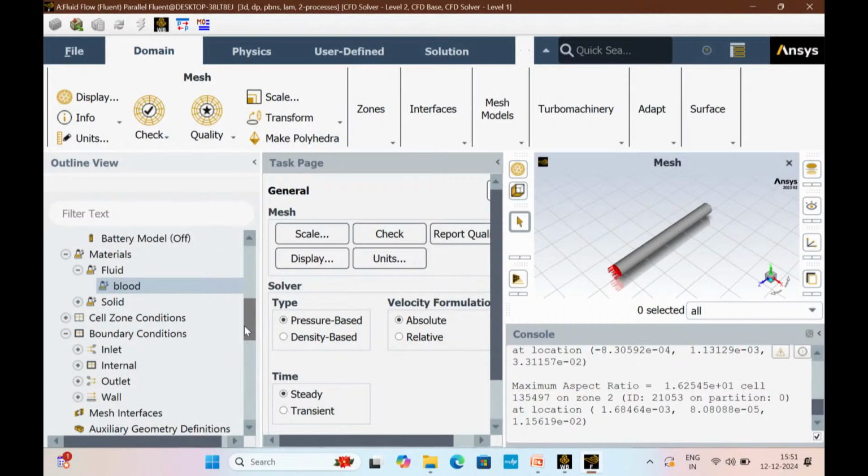So, maybe tomorrow I will be showing the FSI simulation. In that FSI simulation also we will be using 0 pressure only, but just for visualization we can do that. For getting quantitatively accurate results we need to give pulsatile pressure at the outlet. So, we need both pulsatile flow at the inlet and pulsatile pressure at the outlet. Has everybody completed up to this step?